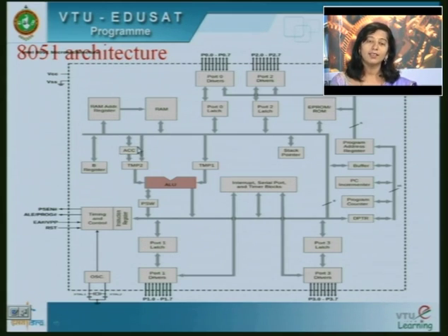Then the output after computing addition or whatever is passed on to a temporary storage register, TMP2. It's a temporary storage register. So you can fetch data from the RAM, pass it on to the accumulator or the B register, maybe 2 different data to each of them, add them, subtract, do whatever, and store the temporary result in this temporary register.